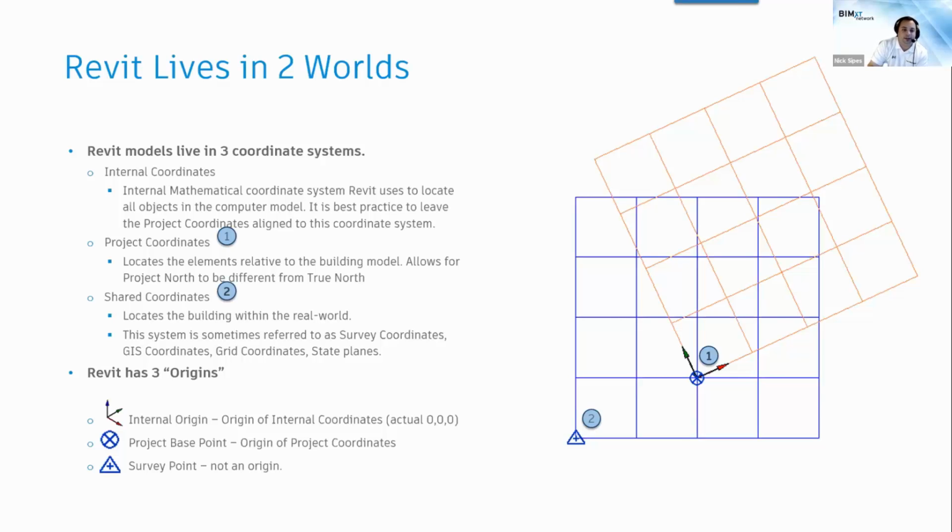There's arguments that can be made to move the project base point away from that, but the big thing to know is that internal origin, that's where that 30-mile radius, that's not really a radius, that's not really 30 miles limitation comes from. So anyway,